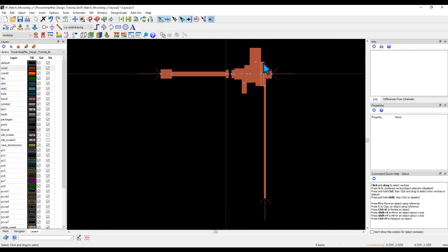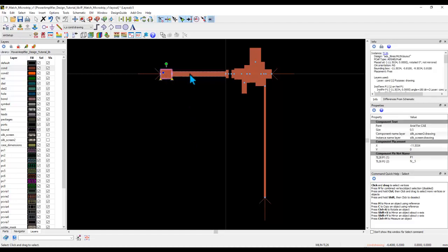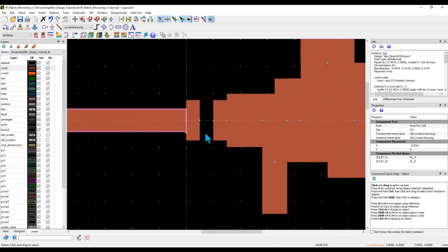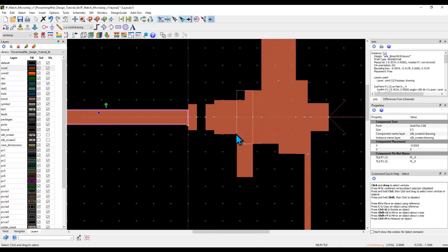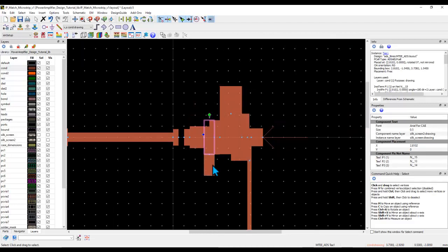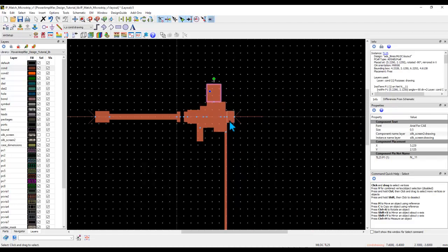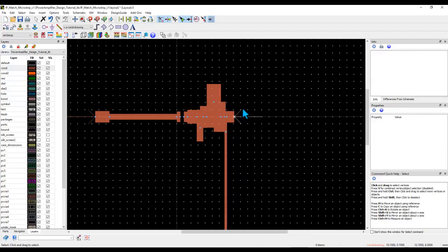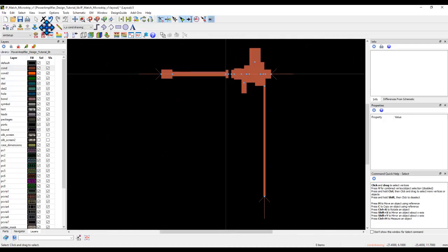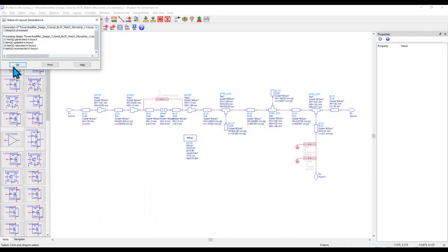And surely so, you can see all the layout comes out very nicely. You have the transmission line and you also have the pad for the series capacitor, which you saw, and these are all double stub matching, open circuit matching, and this is the DC bias line, and this is the series line where my gate of the device and corresponding line and stability resistor will get connected. So very simply, I came up with the layout for the input matching.